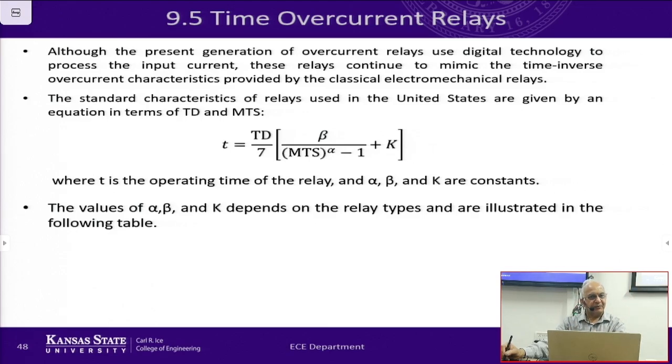And how do we do that? This particular equation gives you the time of operation. T is the time, TD is the time dial, and MTS is the multiple of tap setting that we talked about.